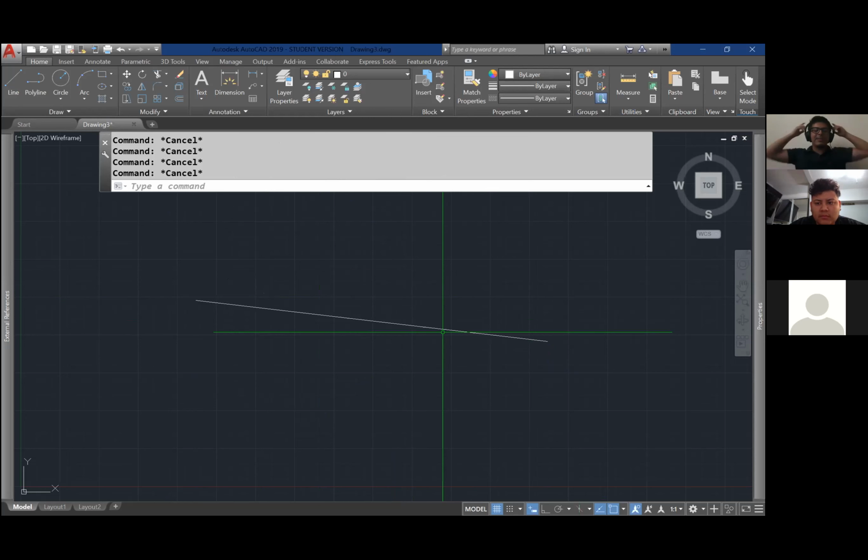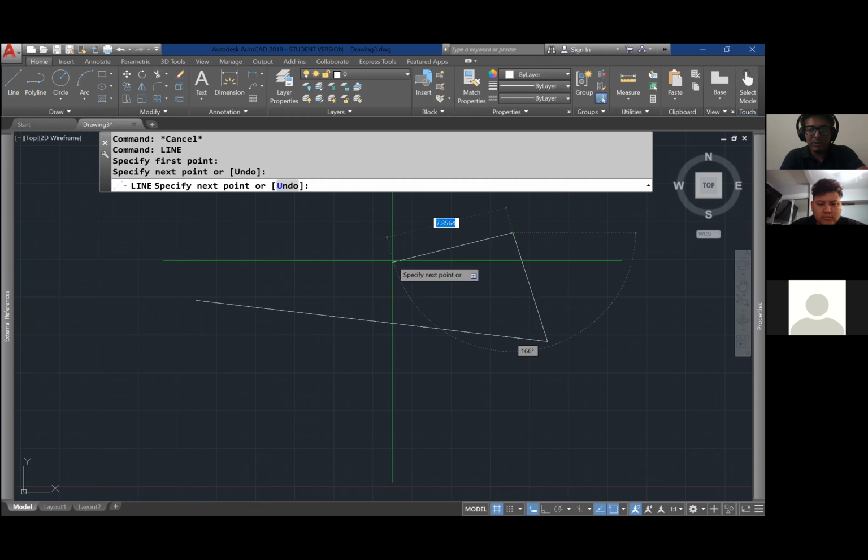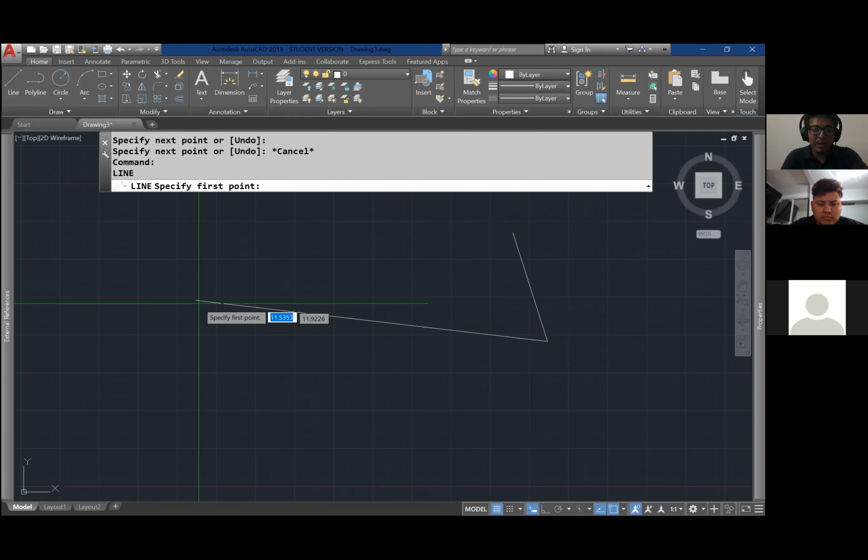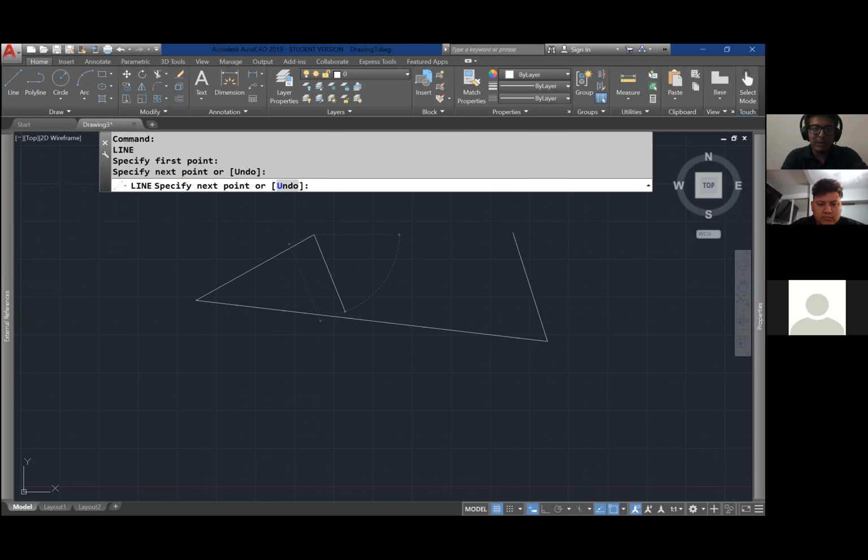And then here's the other thing. There's this thing called snapping. If you've used other programs, you know what that does. So say I have this line here. I type line as well. And now you'll see these little green things pop up, like that green little triangle. And I go over here, you'll see this green little box. You'll see these green little boxes over here. And those are to snap. You can draw from that point. You just grab it and you move it. You can draw from these little endpoints over here. You can also draw, if you type line, from midpoints.